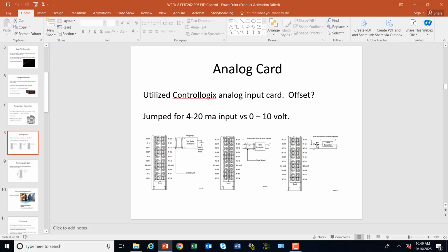I like the way that we did this. We ran 3 wires out of this: a banana lead out of the voltage, out of the current, and out of the return. If we want to run current, we just daisy chain those on top of each other as banana jacks. But if we want voltage, we just ignore the current and use the voltage.